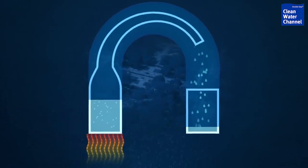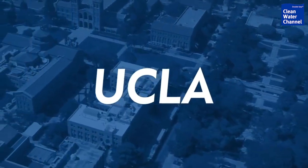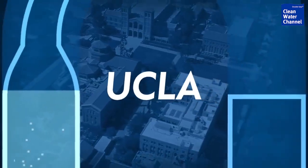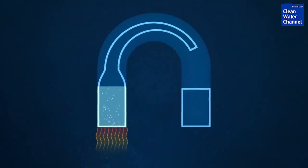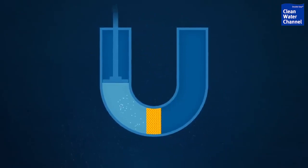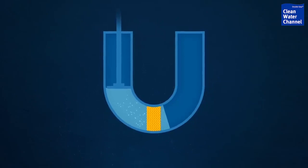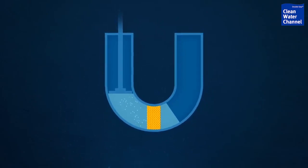But in the 60s, we were able to develop reverse osmosis processes at UCLA, and these have now started to dominate the market. So one of the big chief differences between the two is reverse osmosis doesn't use heat, doesn't boil anything. You're really just pressurizing the water to a tremendous amount, and you're forcing it through a membrane where it doesn't want to go. It wants to stay with the salt, but with this high pressure, it is forced to separate from the salt.